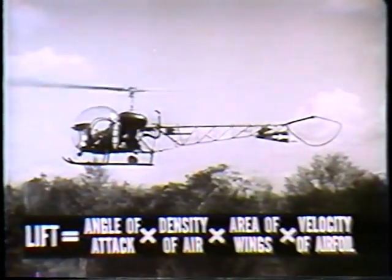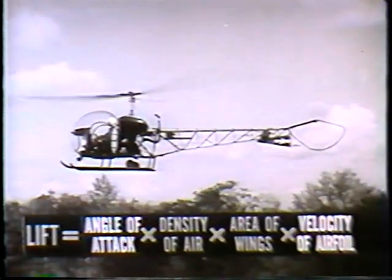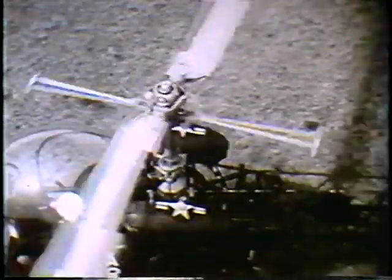Of the four factors which give you lift, the pilot can control only two: angle of attack and velocity of the airfoil. In a helicopter, the velocity of the airfoil results basically from the rotation of the rotor blades. A rotor blade is a wing or airfoil which flies in a circle, thus the term rotary wing. The chief characteristic of rotary wing flight is that relative wind and resultant lift is created by the rotation of airfoils through the air.